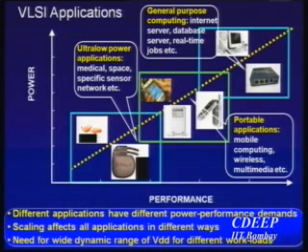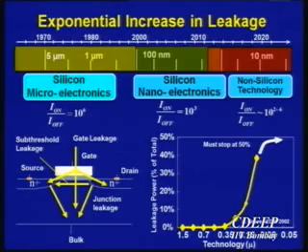The other important thing to note is that if you look at a wide range of applications, and you want to go back and forth in some cases between high performance mode, which is higher load, versus low performance mode, which is lower load condition, one of the best things to do is some sort of dynamic voltage scaling. That's the underlying theme in most of the things I'm going to talk about, more so in next week's lecture than today's. But today's focus, as I mentioned, is mainly going to be on variations and the scaling of technology.